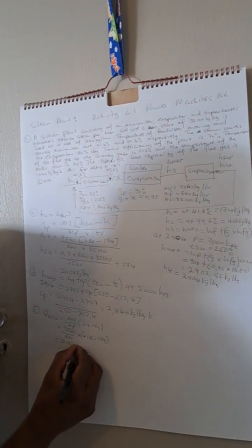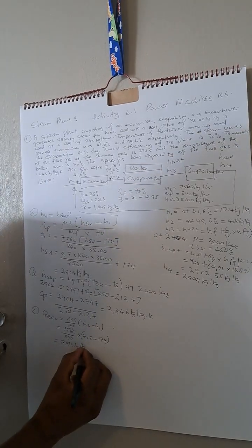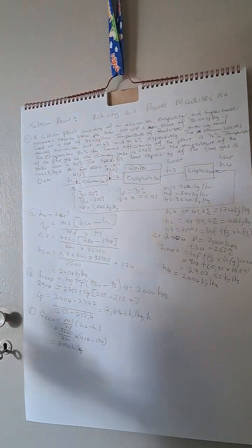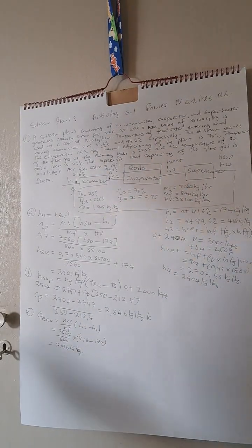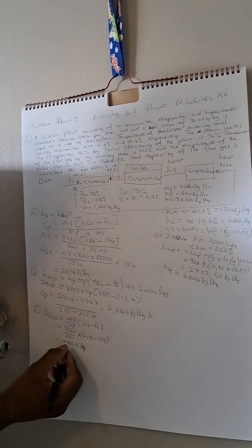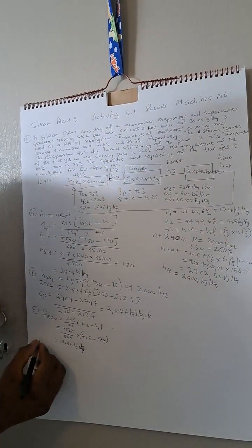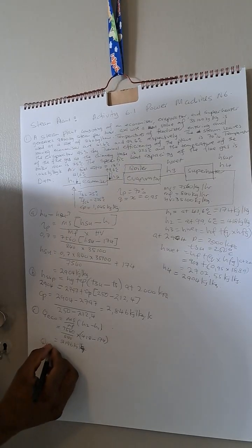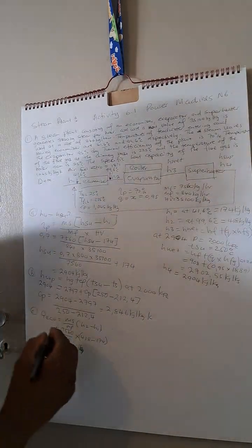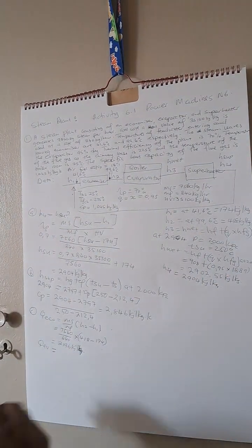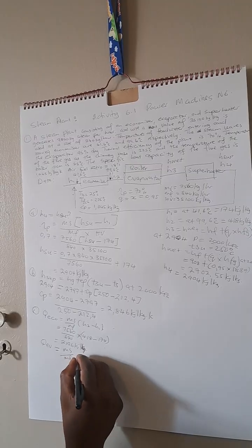So I'm getting my answer as 2196 kilojoules per kg. That's what I'm getting. And then we need our Q evaporator. We do the same thing. Our Q evaporator is Ms over Mf times...